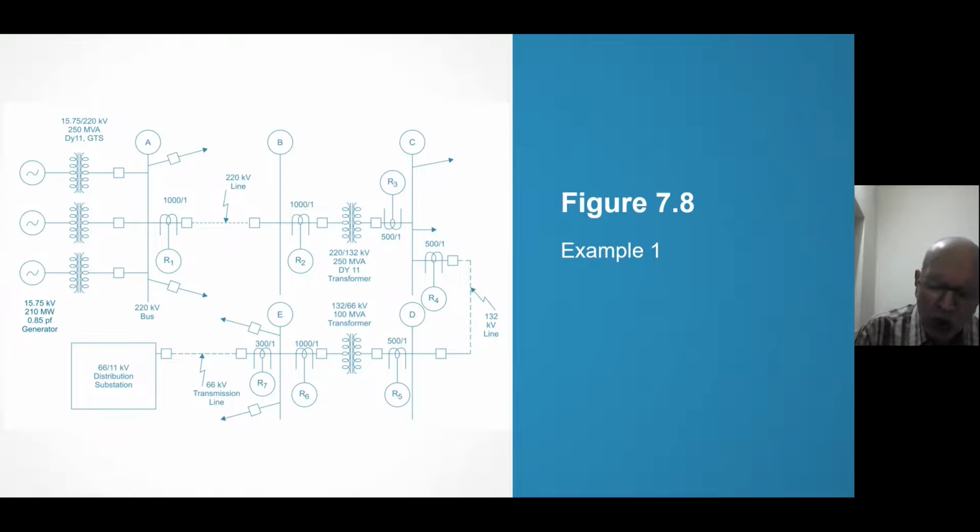I have talked and I will again and again remind that this is a single line diagram. Means R1 is a bundle of 4 relays, 3 phase relays and 1 ground relay. Right? Even if numerical relay is there, the casing is 1, but the settings are different for phase and ground relays.